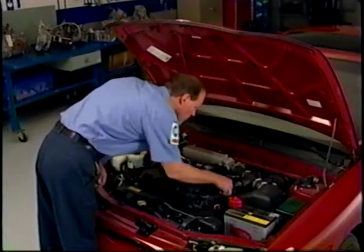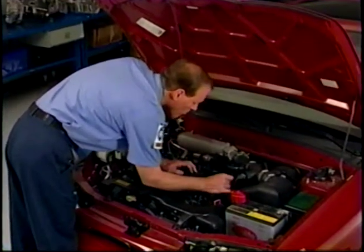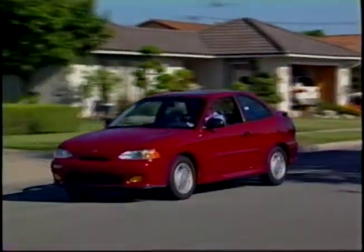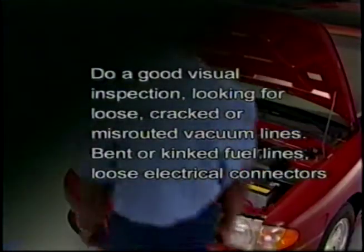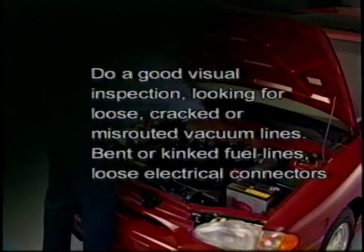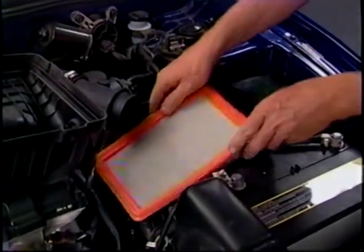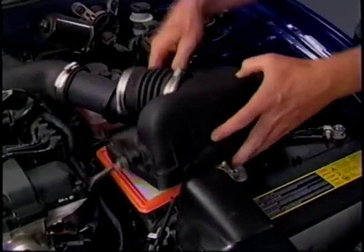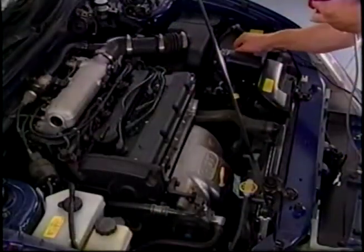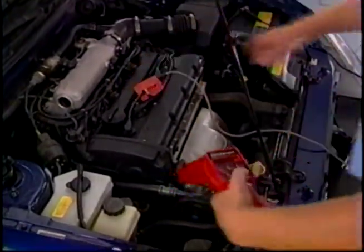The diagnosis of engine performance problems begins with the basics. That's why almost every major manufacturer publishes a basic inspection procedure. Start your diagnosis with a road test to confirm the drivability concern, then do a good visual inspection, looking for loose, cracked, or misrouted vacuum lines, bent or kinked fuel lines, loose electrical connectors, and the condition of the air filter and intake bellows. If any abnormal condition is found during the visual inspection, repair it, then continue with the basic inspection. If everything looks okay, connect a tachometer or a timing light and check the engine idle speed.